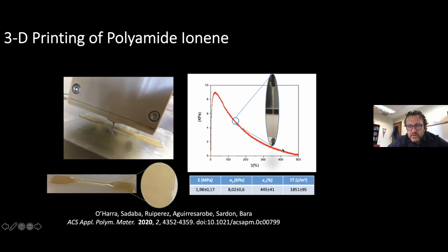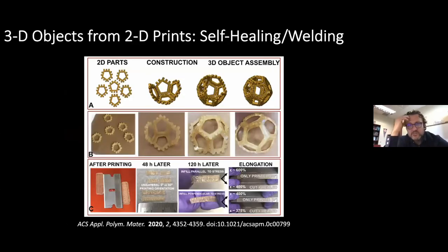So you're able to make these tensile bars, and we're able to stretch them. We see here quite a steep increase in the Young's modulus, and then a much more gradual increase. Probably we can't go further, it's the limit of the machine, in fact. So again, really excellent possibilities for 3D printing. And when we use those self-healing properties, this was quite fascinating.